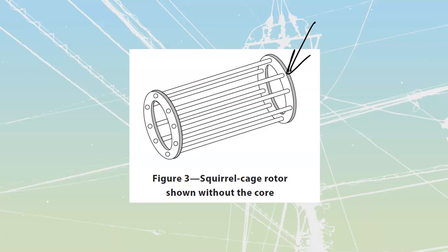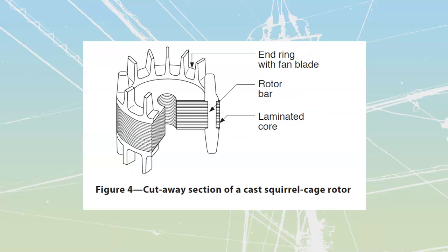In smaller motors, what we will do is cast these things. So they're going to take all these laminations, place the laminations inside of a mold, and then cast in the aluminum. And over here you can see the cutaway that we've got once again the shorting ring that would go all the way around, and through these slots the aluminum just pours through.